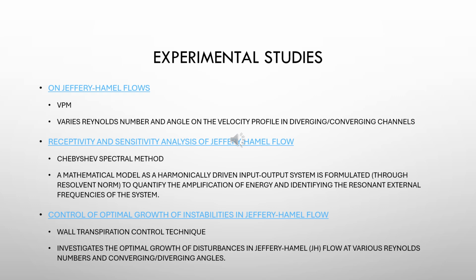The last study for experimental studies addresses how flow control aims to delay the transition process, reducing drag and flow-induced noise. While instabilities in plane channel flows have been extensively studied, the control of instabilities in converging and diverging JH flows has not been addressed. This study numerically investigates the optimal growth of disturbances in Jeffery-Hamel flow at various Reynolds numbers and converging and diverging angles.